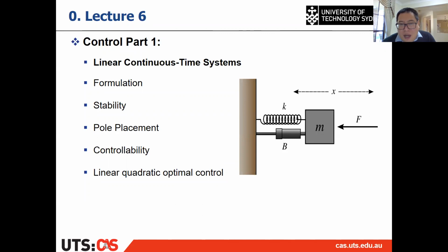Then after you use the state feedback control, you make your control U equal to minus Kx. Then your new A matrix for the state feedback control is A minus BK. Right? Then you can choose a proper K to make your new system A minus BK stable. So that is the pole placement.